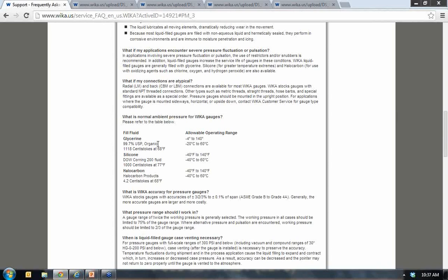And then for low pressure, that would mean that we're either using a seal gauge or a low pressure capsule gauge. And I would just need to make sure that it could handle that kind of installation. It would probably be the combination of the two, though. You'd also have to make sure that the diaphragm seal has enough displacement to handle the low pressure gauge, so it would probably be a very large diaphragm. There are some intricacies there that would have to be worked through to make sure that application worked, but it can be done.